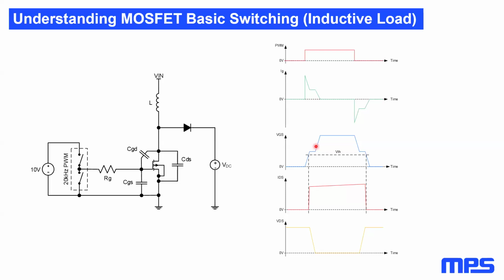Entering into the third period of the turn-on procedure, the gate is already charged at a sufficient voltage, the Miller plateau, to carry the entire load current, and the rectifier diode is turned off. That now allows the drain voltage to fall.